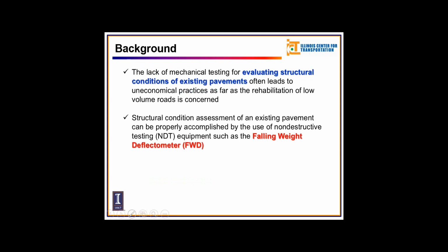Also, since they don't do any kind of structural assessment testing, no mechanical testing for evaluating the structural condition of existing pavements, this often leads to uneconomical practices as far as the rehabilitation of the low volume road is concerned. Because sometimes, if the pavement is actually in very good condition, the design will come up with a much thicker design requirement, which was not needed. So you will have an expensive cost of construction.